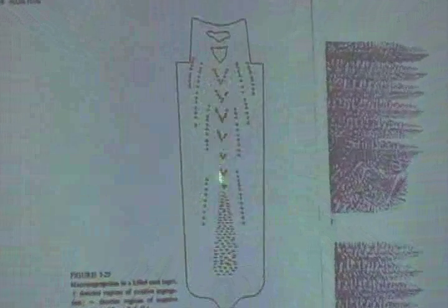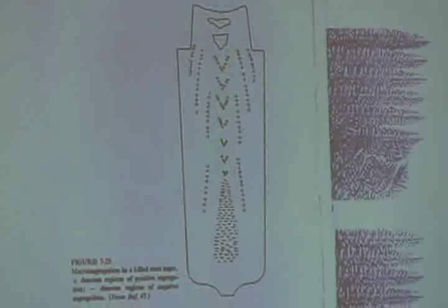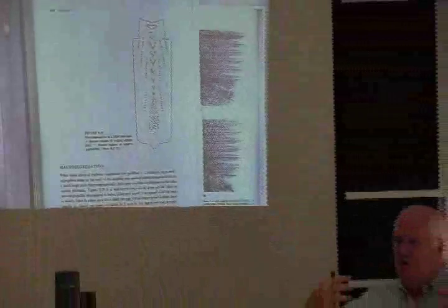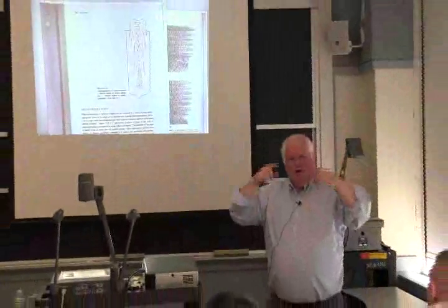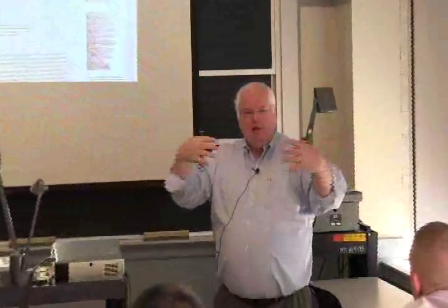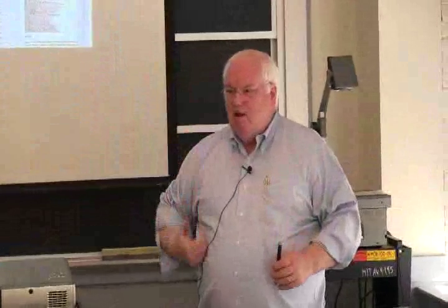The ones on the outside, the ones in the center are called V segregation, and it's basically just due to fluid flow. But fluid flow among the dendrites. This is fluid flow between the solid limbs of the casting alloy, so it gets sort of messy, okay, to analyze. But people have measured it, and they probably still are analyzing it.